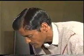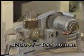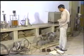Switch on the vibrating machine. This vibrating machine has standard vibrations of 1200 plus minus 400 vibrations per minute. The cement cubes are compacted by giving standard vibrations for 2 minutes. Switch off the vibrating machine after the stipulated time of 2 minutes.